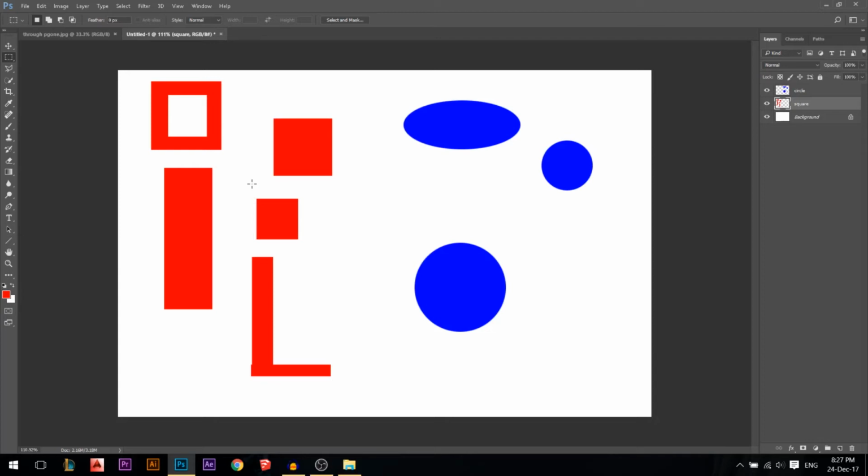I want you to be aware that if you have a selection, pressing Shift before will add the plus. Then now I left Shift. I'm not pressing Shift anymore, but we're already in the plus mode. However, if I press Shift again, it will maintain our square. The same goes for Alt. If you press Alt, it will minus. However, if you leave it and then press it again, it will make the center where the square is growing from. So I don't want you to get confused about Shift and Alt, because they are used before you press click and after you press click. So keep that in mind.